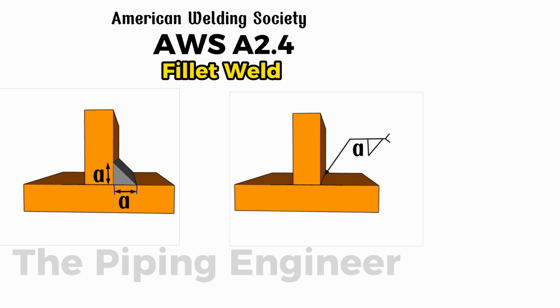What that number's telling you is the leg size of the weld, basically, the length of the sides. For example, if you see an 8 right in front of the symbol, that means the leg size on both sides of that fillet weld needs to be 8 mm. Or, if you see a 12, then each leg size has to be built out to 12 mm. It's super important for making sure the weld actually matches the prints and holds up to the design specs.